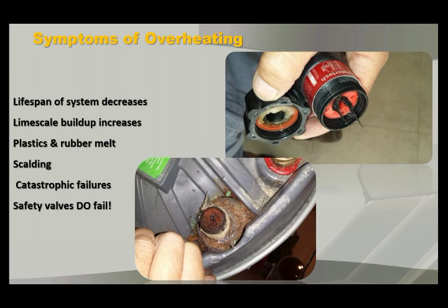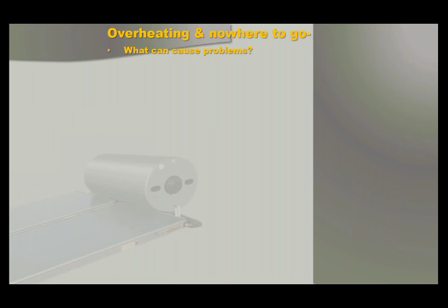That TP from the outside looked perfectly fine. No problem at all. But that thing isn't going anywhere. It's not sensing any temperature. It's not sensing any pressure. And that's why it blew back through this PRV like that. I was called out at about 2 a.m. one night to this problem. A small child had gone to the bathroom and opened a tap, and it was a catastrophe. Nobody got hurt, but anyway. This is just to show you that safety valves do fail. Not all valves are infallible, and not all systems are infallible.